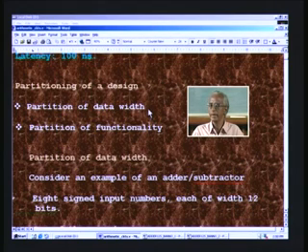That will be faster than adding 16 bits, and you can pipeline here. You can start adding the LSB first, and then in the second clock, in the second register, that is process 2, you can add the MSB. In this fashion you can distribute your entire data width, and there is no hard and fast rule for such division. You have to experiment with it and then arrive at the best possible bifurcation or partitioning. And this is the partition by data width, and next is partition of functionality.